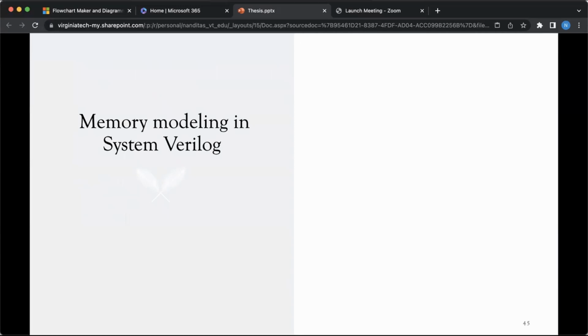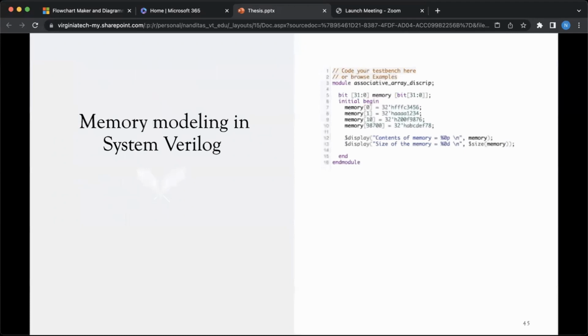The biggest challenge that we faced was to integrate a hash map with Verilog, because conventional memory works on the sensitivity of a clock and a reset with the memory interface. Now, integrating a hash which follows all these signals was a challenge. So what we did was we implemented our memory model in System Verilog. System Verilog is a language which is made on top of Verilog. It has the hardware descriptive language capabilities as well as the software data structures and OOPS concepts.